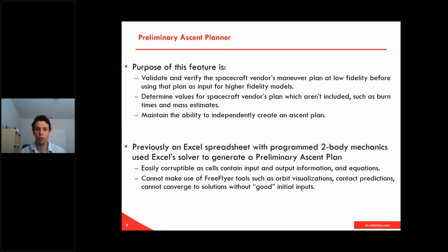Usually we only use two-body spacecraft propagation to basically make sense of how much we need to raise the orbit at each burn. Usually the whole sequence from separation to the geostationary orbit takes 10 burns, and each has to occur at a longitude where we have coverage, and after all the maneuvers, we must reach the target desired longitude.